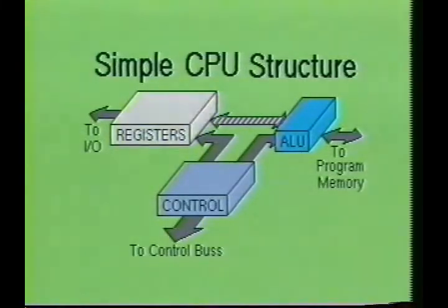You have also seen that the central processing unit contains a register section. The CPU contains several registers that are often called data registers, working registers, or simply scratchpad memories. The register section is used to provide storage for the data being operated on by the arithmetic logic unit. So far, you have seen that the CPU, or central processing unit, contains three basic sections. These were the registers, arithmetic logic unit, and the control section. You have also learned the basic function of each of these sections.